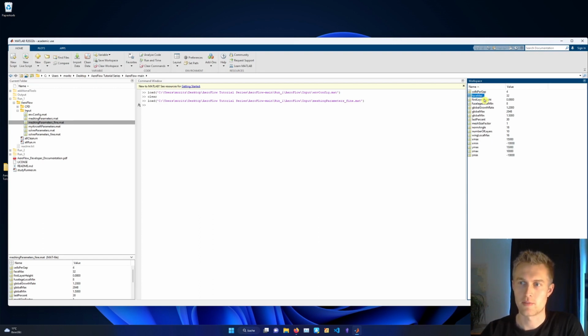Then we've got phase max. So that is a cell size value, and globally every surface cell will have a maximum value of 32 millimeters in that case. And we've got the first layer height in millimeters also. You might want to change that depending on your setup, on your flow conditions. Then you've got fuselage local min. I hope the names are a little bit explanatory already, but on the fuselage part of the geometry, you will have this minimum cell size.